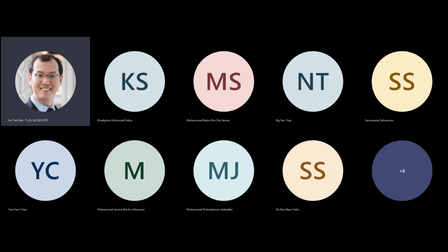And then you put your VDD supply here. This will be connected to a big trace, and this will be connected to the ground. And voila, this is how we build up the individual logic gates on the silicon wafer, except that this is drawn really large. In actual fact, the actual dimension size of this is on the order of nanometers, right?